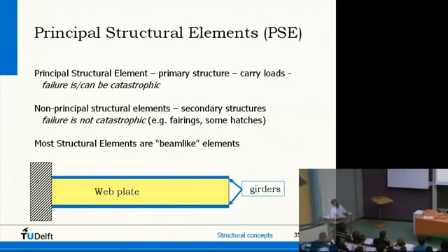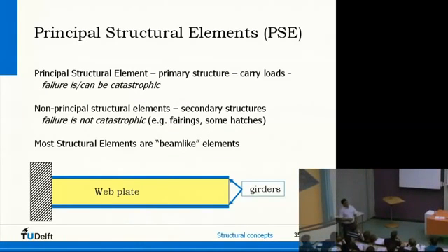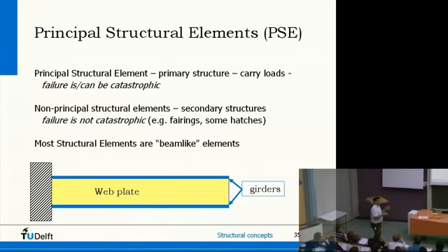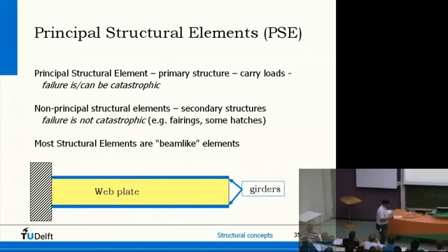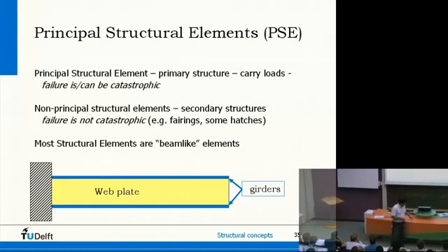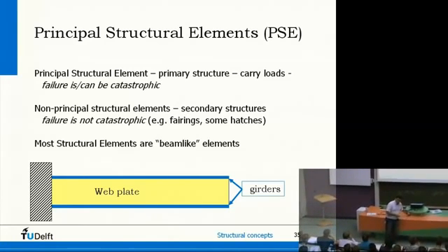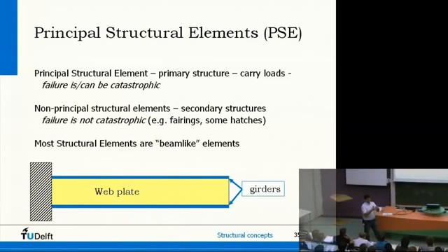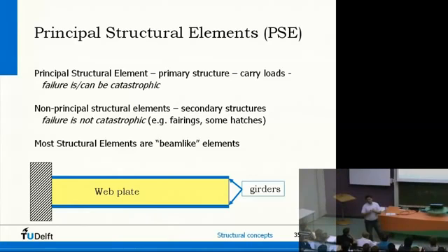That's becoming, by the way, more and more a problem if you are working with composites. Composites are much less flexible in these kinds of things than metals. That's also why, for instance, the 787 had quite some problems during assembly. As soon as you have a mismatch in dimensions of a few millimeters, it is much easier for a metal to accommodate that than for composites.